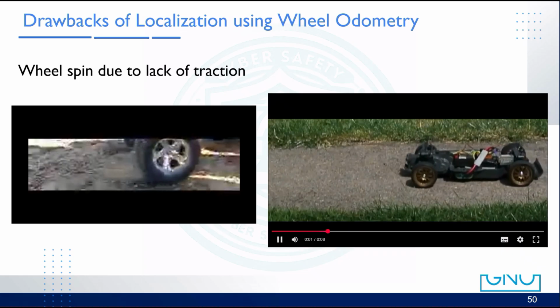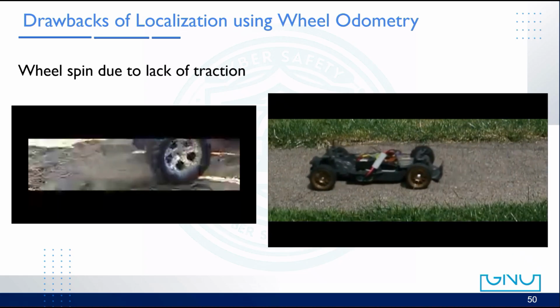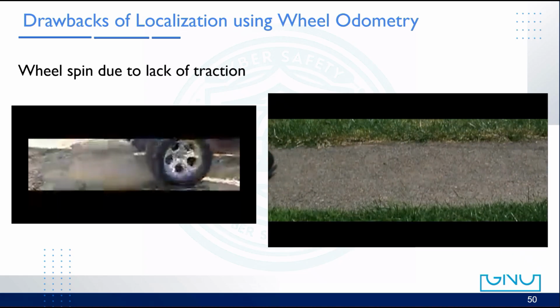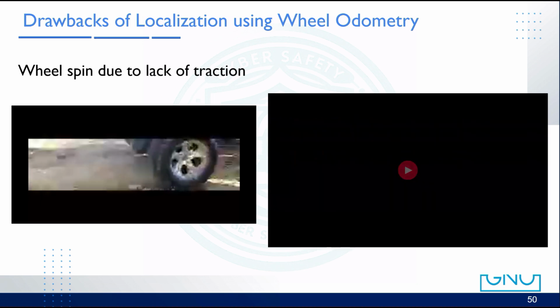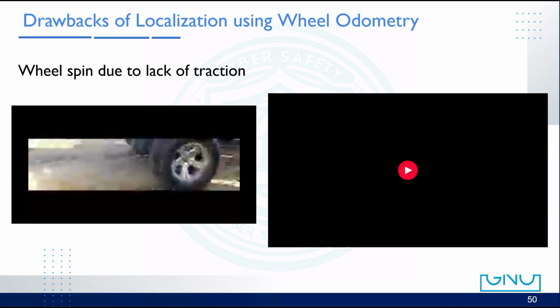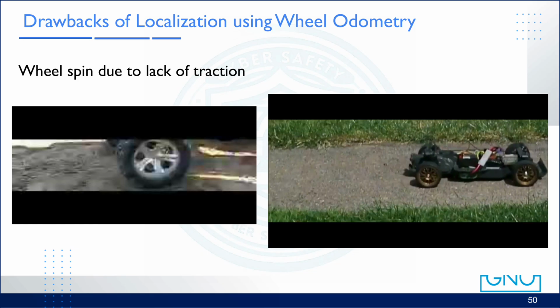First, the measurement itself is imperfect, and because odometry integrates motion over time, even small errors accumulate continuously. The longer the robot drives, the larger the drift becomes. Wheel encoder odometry has an additional problem: wheel slip. High torque motors can cause the wheels to spin in place before the car actually moves. In these situations, the odometry believes the car has moved, even though the wheels are simply slipping, resulting in a